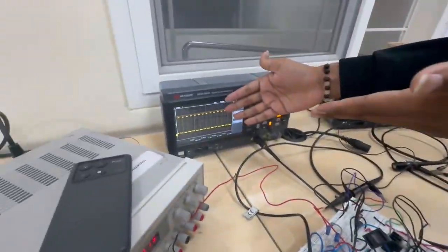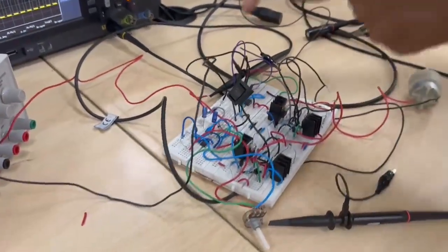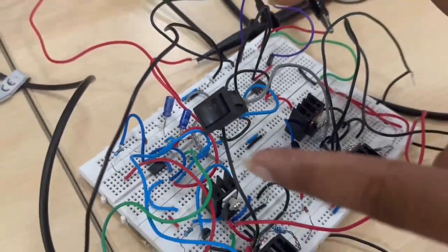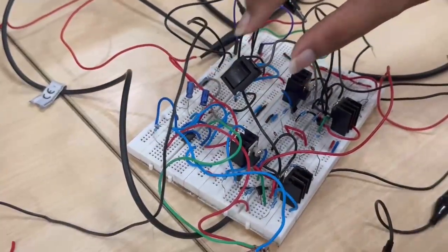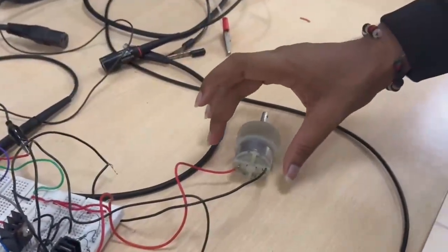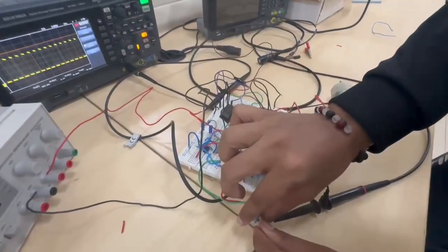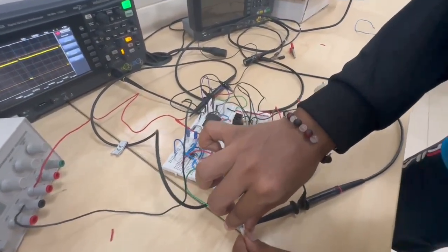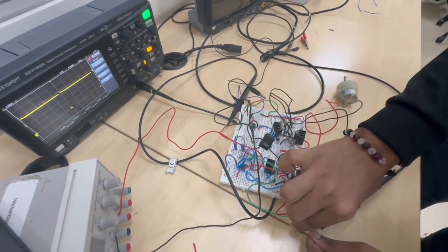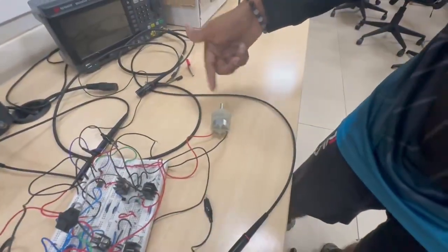After the PWM signal is generated, it is passed to the gate driver input. After the gate driver, the inputs are given to the H bridge through the SPDT switch. The SPDT switch is turned off right now. When we switch it on, the motor runs very slowly because the duty cycle is very low. Let me change the potentiometer. The speed of the motor changes proportionally. Let me lower the duty cycle once again. You can see the duty cycle is being lowered, and the speed has also been lowered.